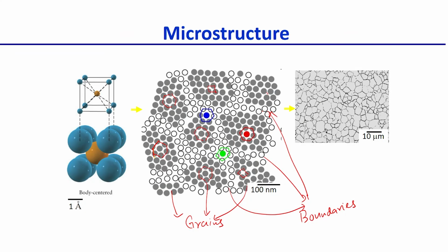Remember, we are assuming one important aspect. We assume each of these regions is a perfect crystal, that means there is no defect within each of these regions, but defects may be present also, God knows, right. Nothing is perfect in this world, but on the other hand, boundaries are imperfect. The arrangement of atoms is haphazard, there are no specific elements or atoms. You can see here this green color region shows a pentagonal arrangement of atoms. Other things are also possible. There is no fixed rule for the arrangement of the atoms in the boundaries, they can vary. So, therefore, this is what your grain structure is.